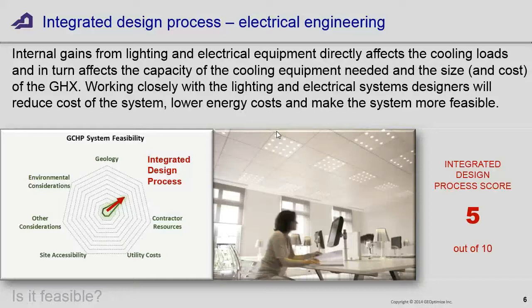When you're extracting energy from the ground, when you're heating the building, the compressor loads actually help heat the building. So about 2/3 or 3/4 of the energy heating your building comes from the ground. So that right away unbalances the system a little bit. Even if the loads are exactly equal over the year, they're unbalanced as soon as you add a compressor to it. Pumping costs. So ideally, you want to try and look at cooling loads that are actually about the same or a little less than the heating loads. If you can get to that point, then the system will run forever and ever and ever.